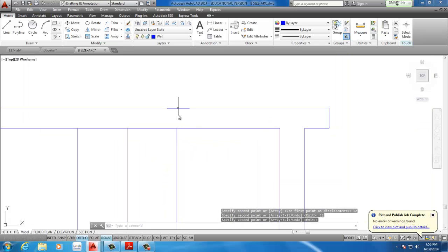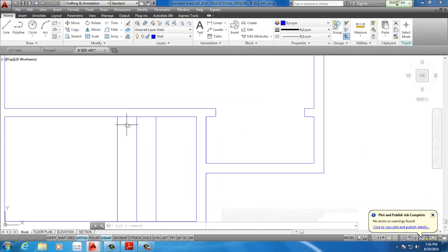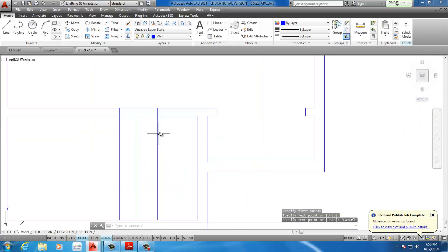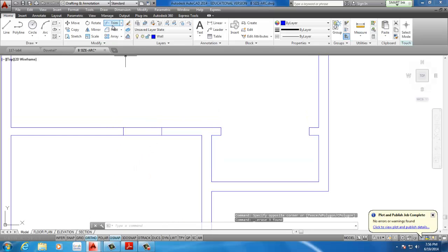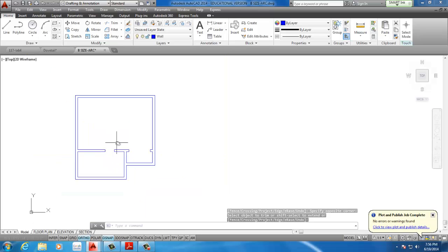And that actually creates the opening for the bathroom door. The only problem is I have to get a complete line across the wall, so I can just add those 2 lines. I snap to the endpoint and so forth. Finally, I remove these 3 lines that I used for reference. I'm going to trim out this opening to give me the opening for the bathroom.